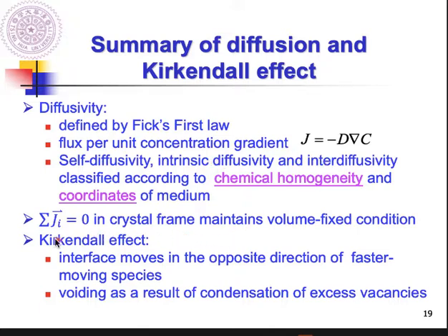And we also introduced a very important concept: the summation of the total flux must be equal to 0, or you can call it the net flux at a specific plane in your materials should be equal to 0. And at the end of this section, we introduced a very famous effect we call the Kirkendall effect, to describe the interdiffusion phenomenon.